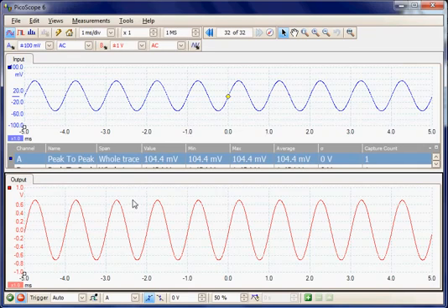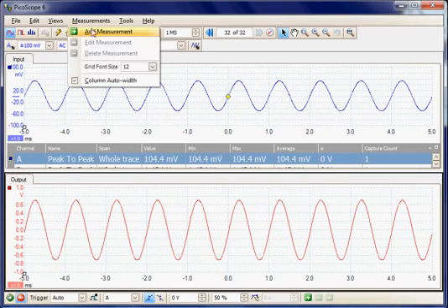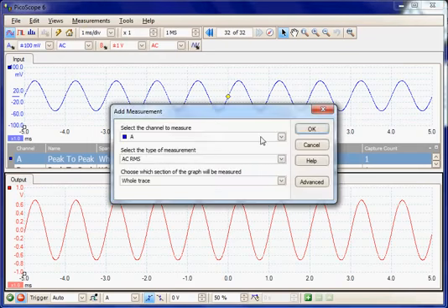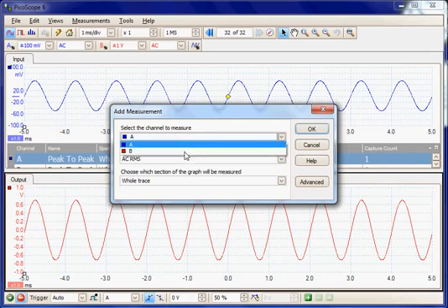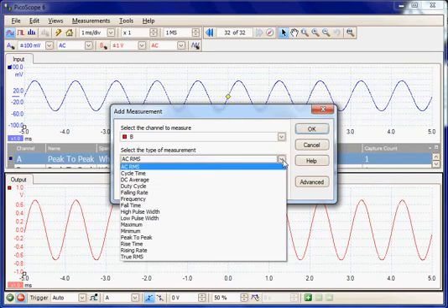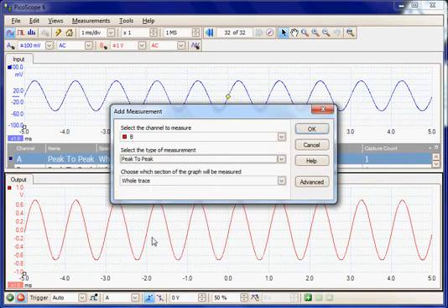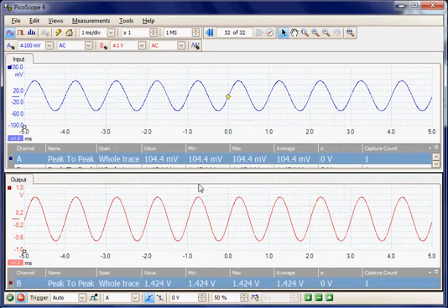Finally we can add the measurement back onto the new panel. Again select the panel and then under the measurements add another measurement, again channel B and measure the peak-to-peak value. So here we're performing the same measurement, the input level, the output level, but now as two separate views. So this is a choice on the documentation type of view required.